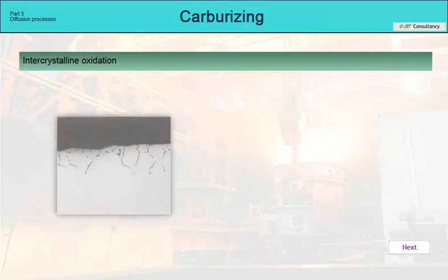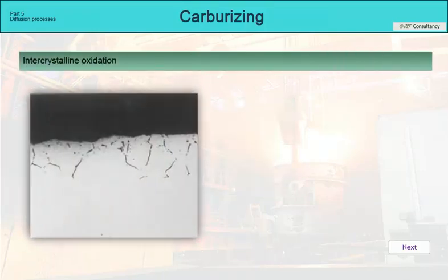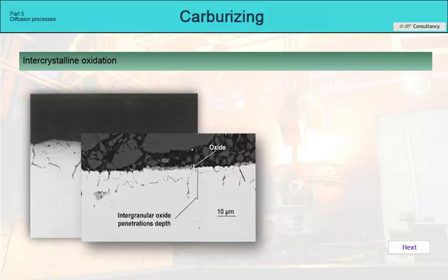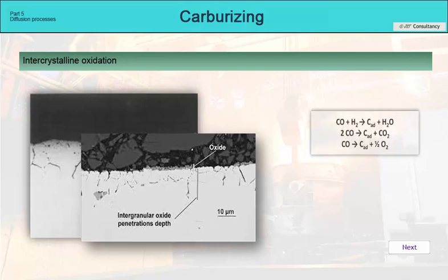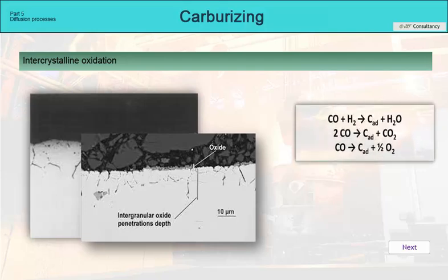Another problem that we have to face in carburizing is internal oxidation. We cannot avoid this in carburizing processes in endo- or nitrogen-methanol atmospheres. The atmosphere always contains a proportion of water vapor or directly oxygen. Finally, the measurement of the carbon potential with an oxygen probe also indicates that oxygen is present in the atmosphere.